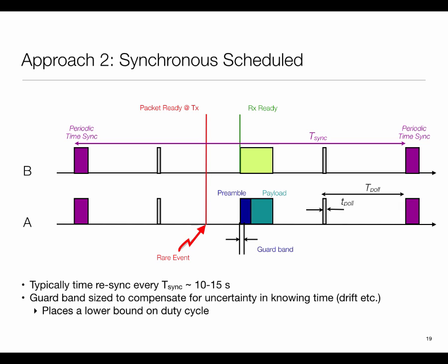A lot of protocols operate in this way, where every so often there is a heartbeat which one node will send out, other nodes will hear, and they'll all set their clocks, so that they have a common notion of time, and whenever they poll at the same time, and whenever I'm sending, I'm sending in that particular time slot. So I can proactively do time synchronization.